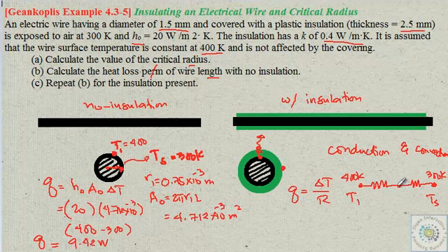Now we don't know yet the temperature in the middle, but we don't really care for that because we could lump this into one resistance. Then we can solve for what will be Q passing through this resistance. We can solve for Q if we are able to get the overall resistance. Let me just have this: this will be the resistance by the conduction through this insulation, and the other one will be the convective resistance.